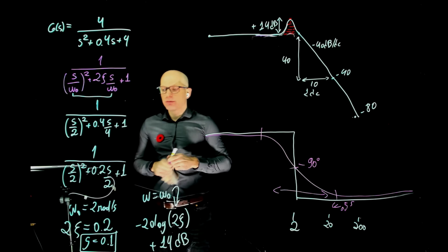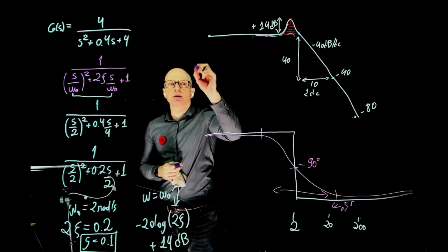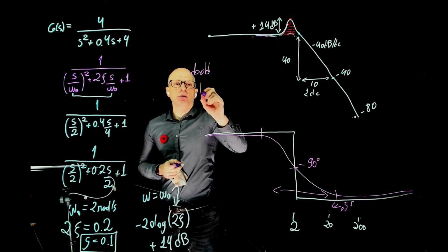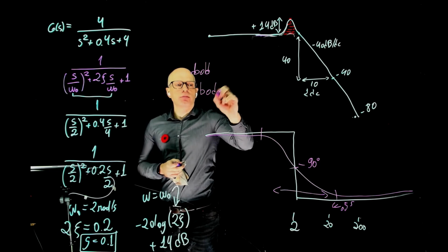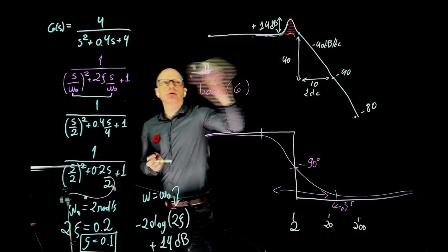And if you want to confirm this, again, just define your function G of s as a function of s, and then do Bode G in MATLAB, and it will plot the Bode plot for you.